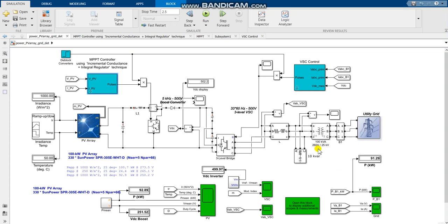This 260 volts is stepped up to 25 kilovolts through a transformer and sent out to the utility grid for high voltage power transmission. One advantageous thing about this is that by significantly increasing the voltage, you are significantly decreasing the current. This reduces power losses as it is transmitted through the wires of the utility grid.